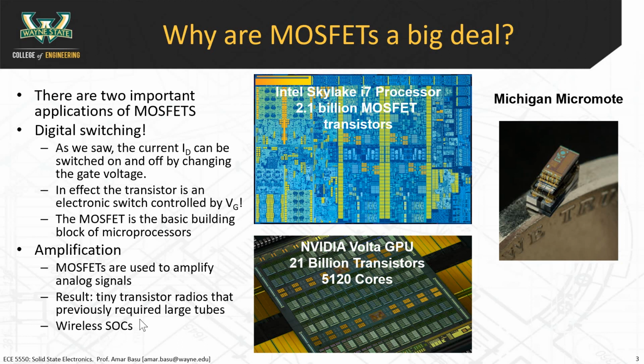One of the big things that happened in the late 90s to early 2000s was the ability to make amplifier chips out of the traditional MOSFET. Usually MOSFETs weren't as good at amplification as BJTs, so specifically it was difficult to get them to work at fast speeds in the 2.4 gigahertz range, which is required for cellular radio. It's required for Wi-Fi, Bluetooth, things like that. But sometime in the late 90s and early 2000s, there were companies that figured out how to make radios with MOSFETs.